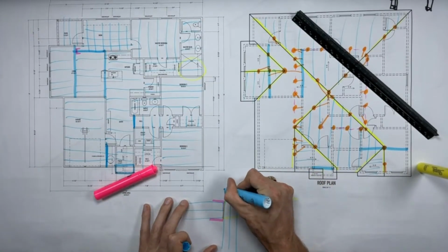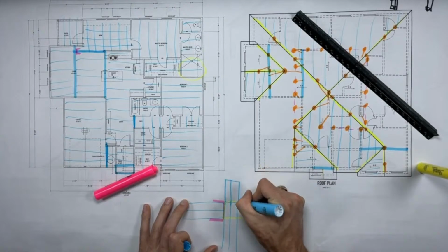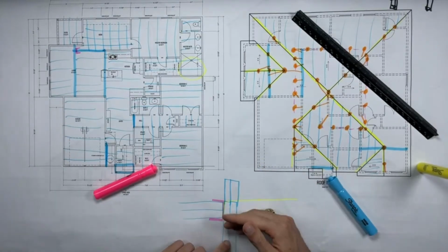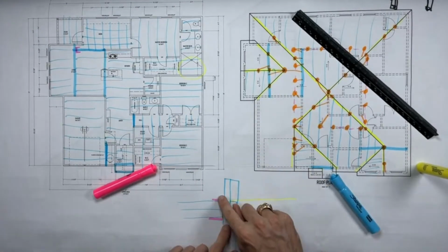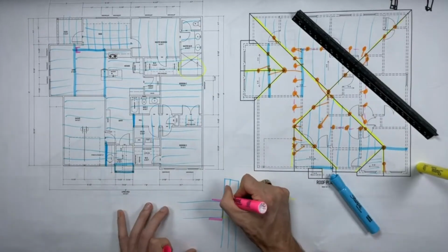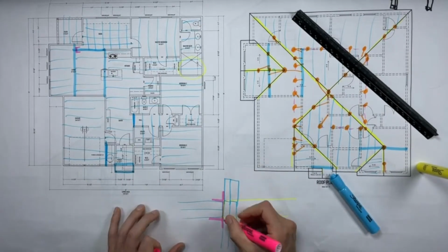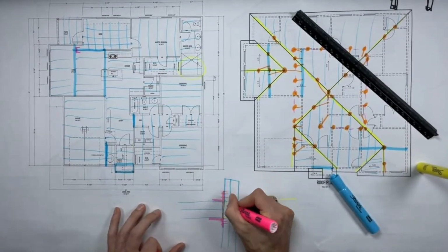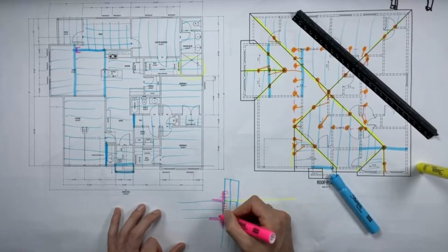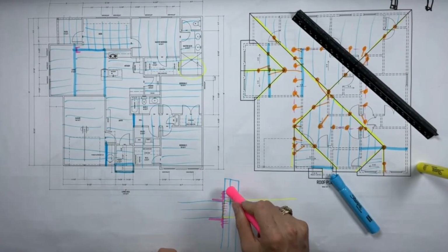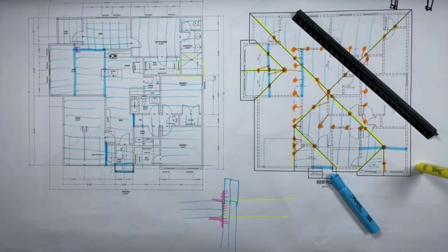They'll just run the beams long and let it sit up in the attic, and no one's ever going to care. So if I have the beam running long, I could use a face-mounted hanger, and the flanges come out to this side, and then they get nailed in like this. So you wouldn't have to nail inside here. You would just do it on the outsides if you have extra wood. But you've got to think about that while you're framing this.